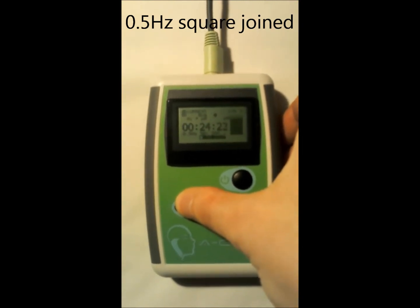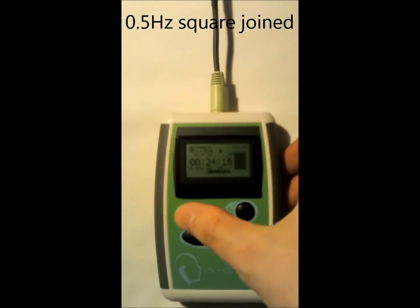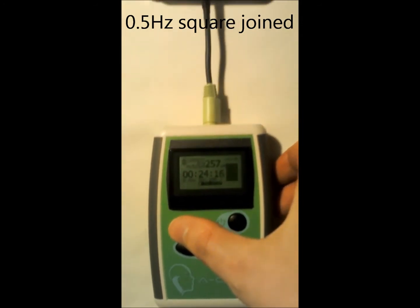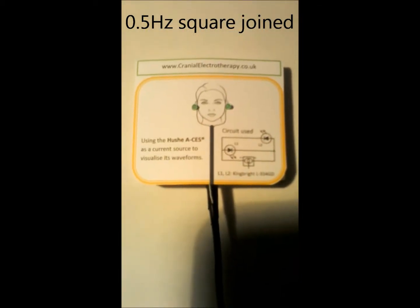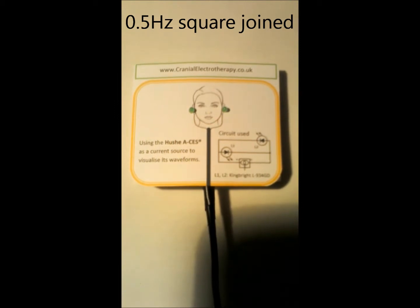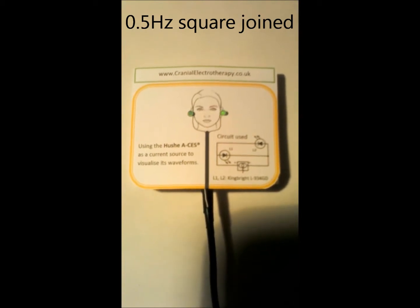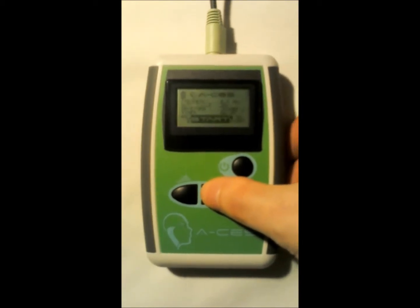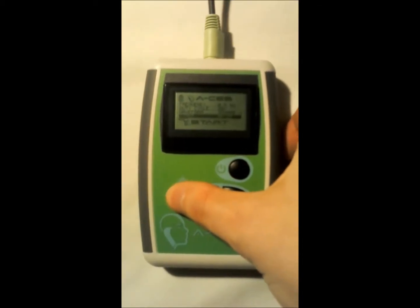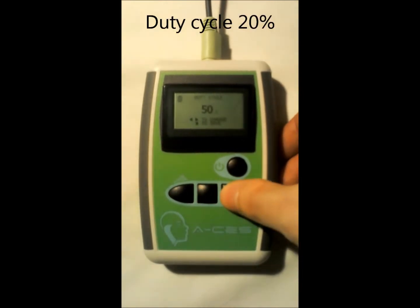Raising it up to level 10 so it's most visible. Now you can clearly see the joined type waveform. Half of the time it's active with either one or the other on, and half the time it's off with nothing happening. Next, I'm going to reduce the duty cycle from 50% to 20%. This should result in a longer off period, which will show up as shorter flashes from the LEDs.